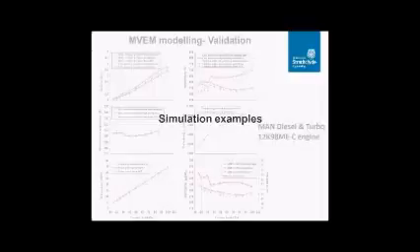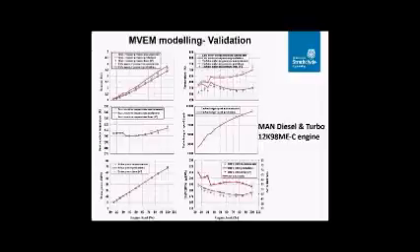This is a two-stroke marine diesel engine from MAN Diesel and Turbo, which was simulated using the mean value model. The engine steady-state operation was examined, covering the operating region from 50 to 100% load. A set of the predicted engine performance parameters, including the receiver pressures and temperatures, the temperature of the exhaust gas exiting the engine, the turbocharger speed, the brake-specific fuel consumption, the brake power, and the total air-to-fuel ratio is presented in this figure.